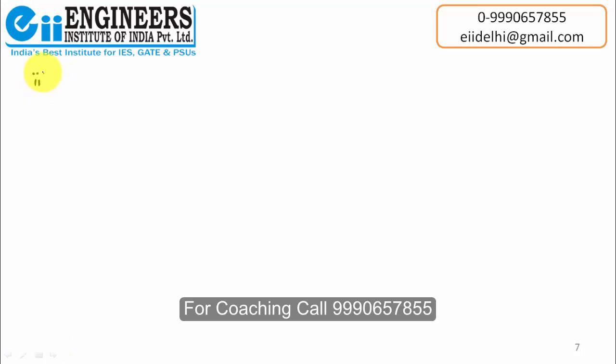Next important index property is specific gravity. We talked about specific gravity in our last lecture. The procedure of finding the specific gravity is the same as that of the pycnometer water content determination, except that in this case we take the dry soil.